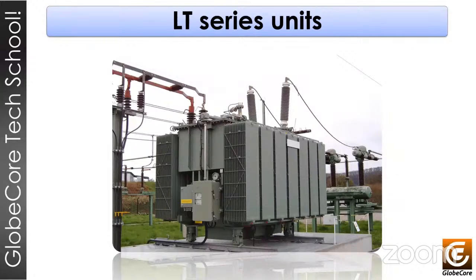Problems with electrical insulation are one of the main causes of transformer failure. Transformers require several electrical insulation strategies to function properly. Transformer oil not only cools the transformer, but it is also a strong dielectric and prevents occurrences of electrical arcs, which can result from high voltage.